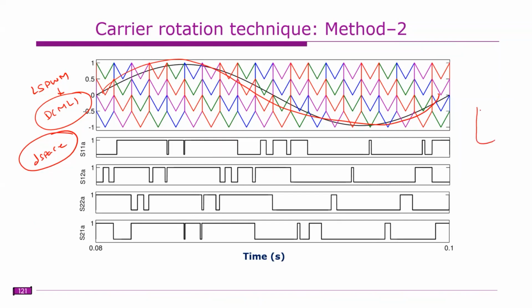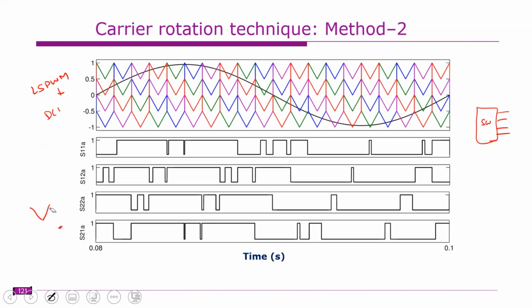So the simple thing, we have some selector switch. Based on that selector switch, we can add an offset. For example, this is the same carrier. If you add 0.5 or subtract 0.4 to that, this value will be reduced. So this is how the carriers are generated.